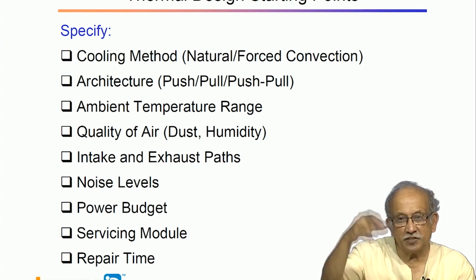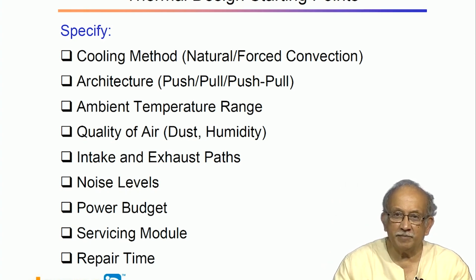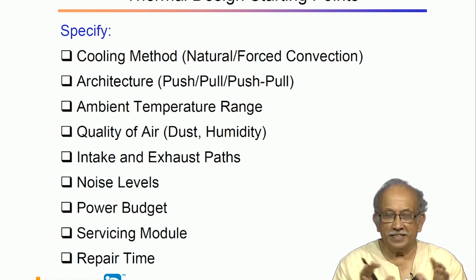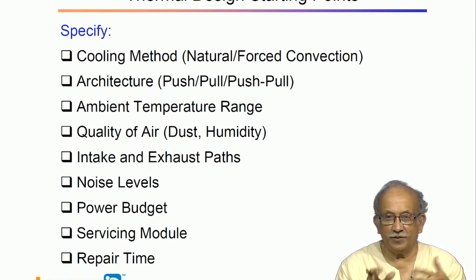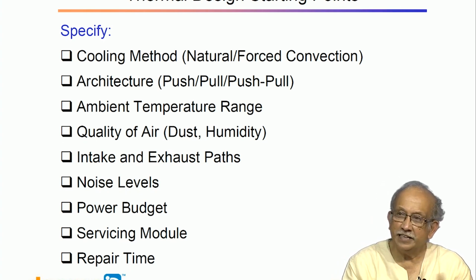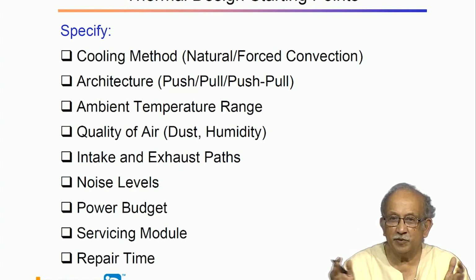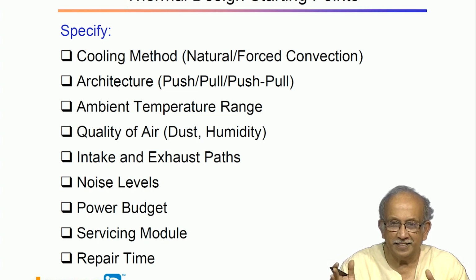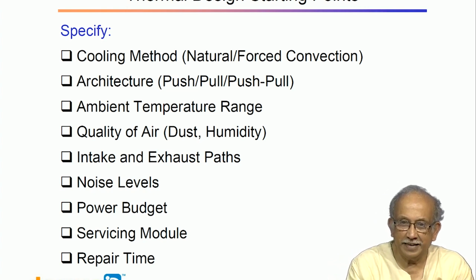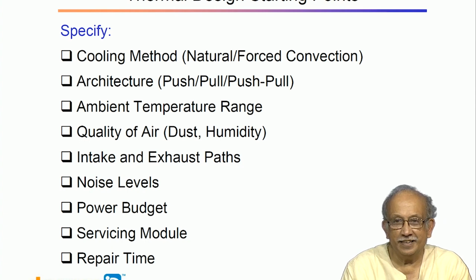And if we just put an exhaust fan, chances are, in spite of the best attempt to make the air flow around wherever you want, it will find a leakage path, short circuit itself, and go away. So, beautiful noisy exhaust fans, clogged filters and hot equipment.